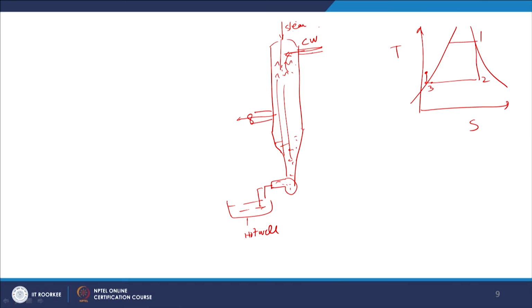So, we have to ensure that the entire steam is condensed. Some undercooling will be there practically, right, but it has to be minimized, because anyway when we are compressing the saturated water, it is turning into subcooled water. So subcooling is not required here. So a good condenser design ensures that only the latent heat of the steam is taken away, not the sensible heat. So here also in a parallel flow, it is collected and it is sent to the boiler.